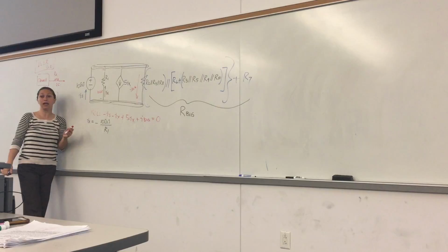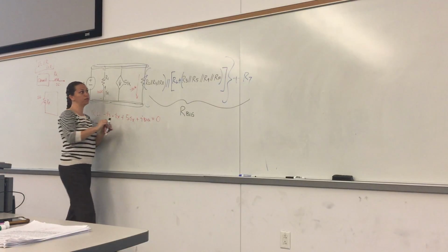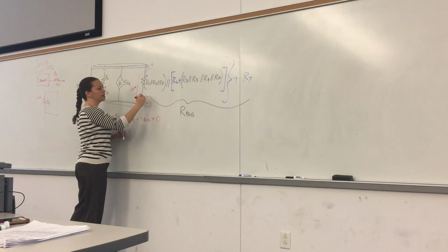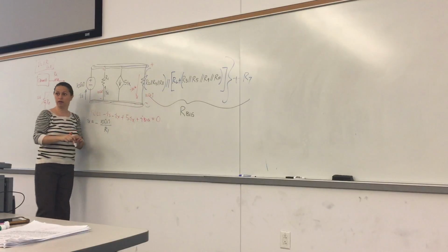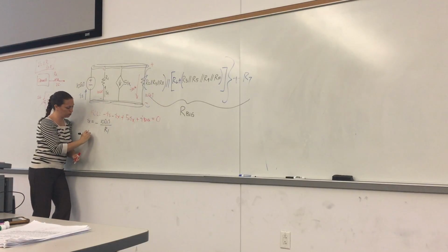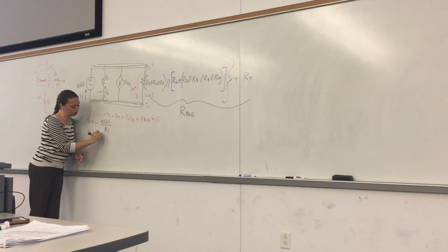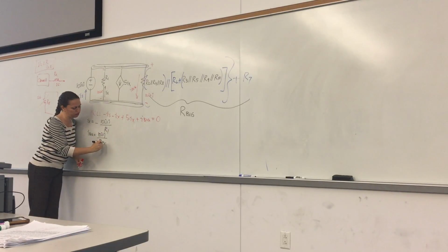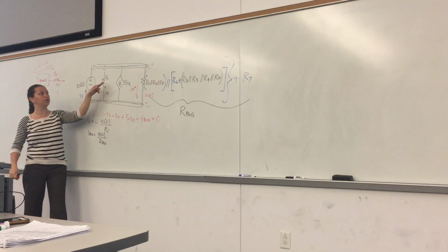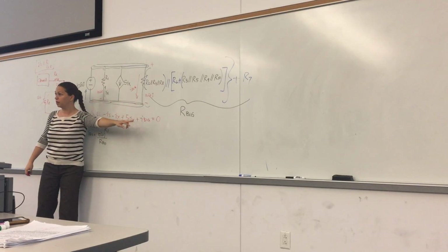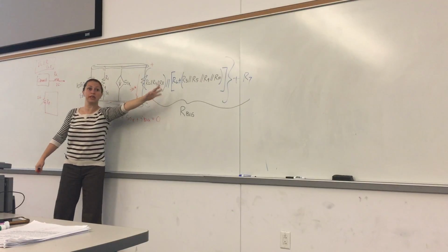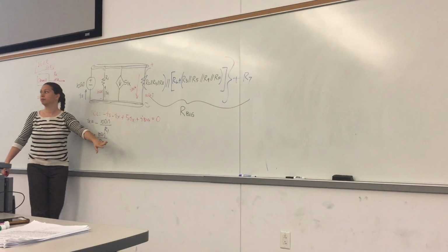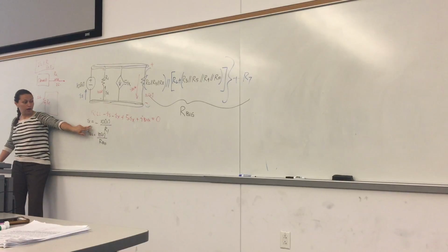Well, same way. Do I know I big? No. We just have to get the equivalent resistance. Well, do I know this voltage? Yeah, it's again 10 volts, right? Same deal here. So I big is also equal to 10 volts over, this time in passive sign convention, R big. I don't have it here, but we know the values of R1 and R big, right? That's already given, and that we calculated. Assume that. So I got IX.